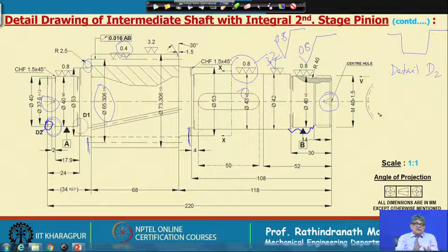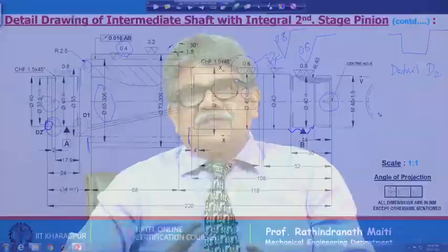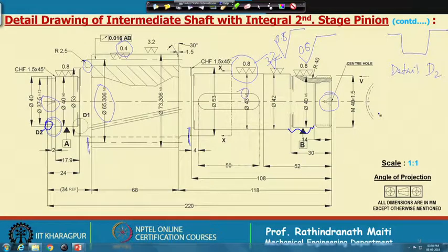There are more details with the manufacturers; I have just this idea and I am giving it to you. Sometimes, instead of the inclined arrow, or along with it, there are two circles, one dot, one center and one circle drawn, and then also some value is there. That means what the eccentricity might be between these two centers, just to maintain the cylindricity of these gears.